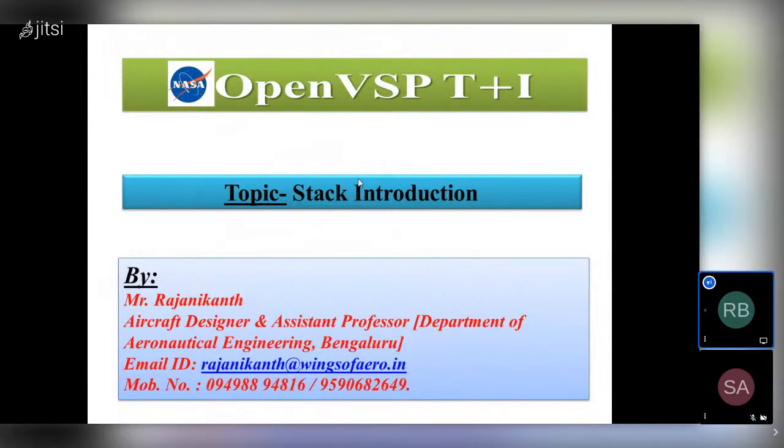Creating a normal stack. Here I will be showing how to create a normal stack for an aeroplane. Stack is one kind of component. By using that component you can create an engine or different kinds of geometries, as per your requirement, especially for your aircraft. Stack is one of the fundamental components in OpenVSP and is useful for modeling various geometrical requirements.